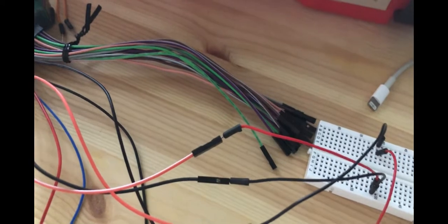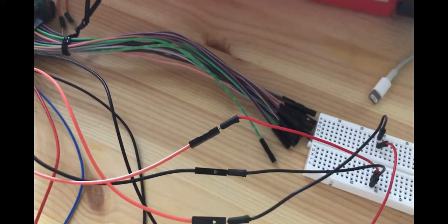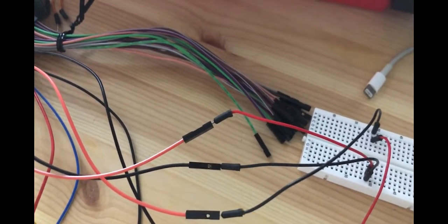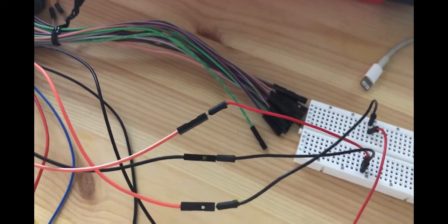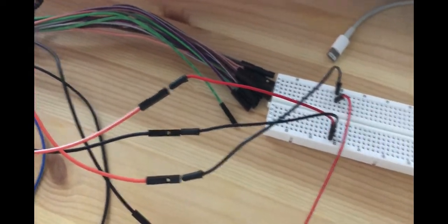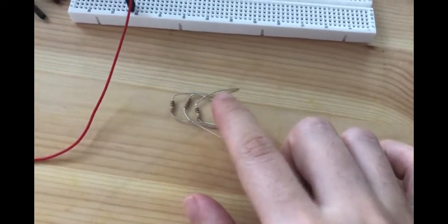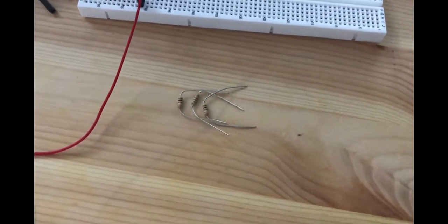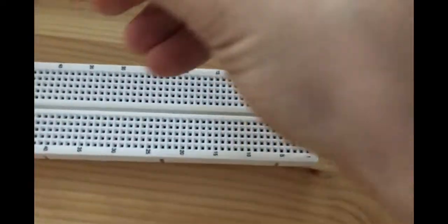The next part of the question, meaning 3.3, is asking you to construct a circuit given in figure 2 and then calculate the voltage across resistor R3. So what you need to do is to pick 300 ohm resistors, as you can see in figure 2. Then you build the circuit this way.